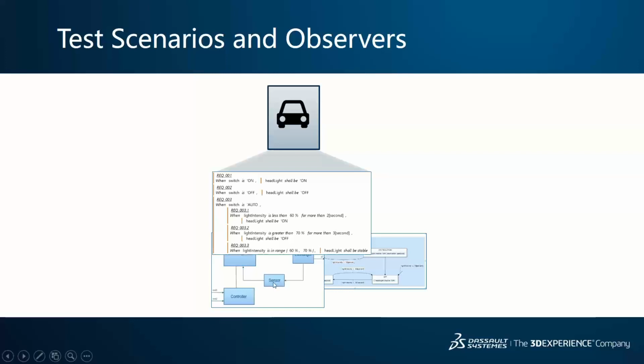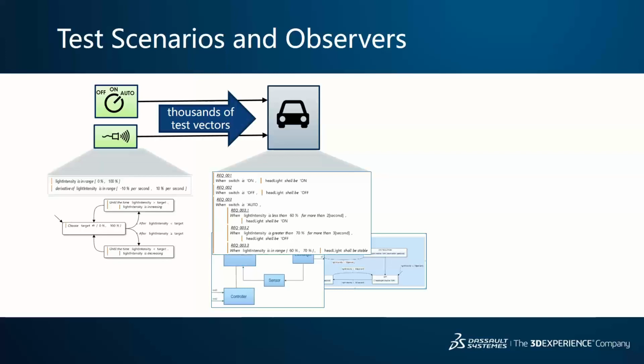And when you want to define the expected behavior of the block, then you can write textual requirements and/or state machines, or a free combination of both. Simulating a spec means you send inputs and observe the answer. So in Stimulus, you will be able to create test scenarios, use cases, if you will, under the form basically of a set of constraints on the inputs. And out of this set of constraints, here a combination of text and state machine, you generate as many test vectors, as many combinations of inputs as you like.